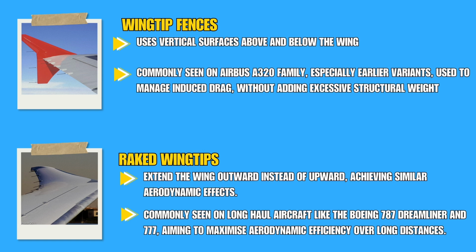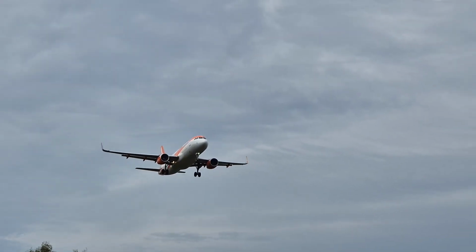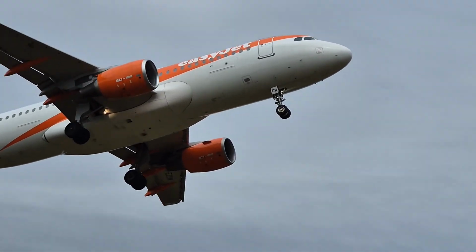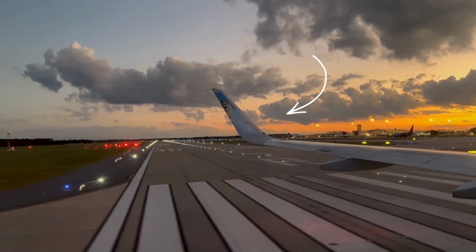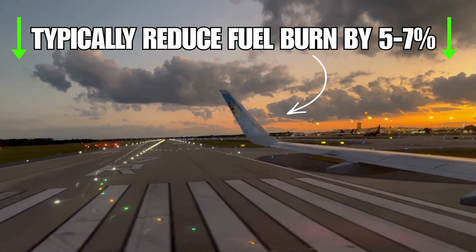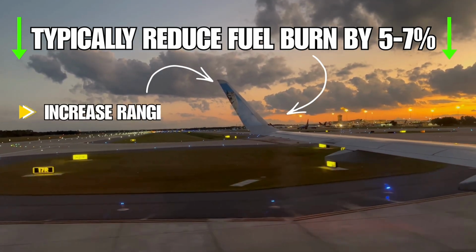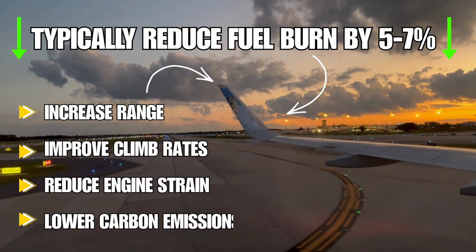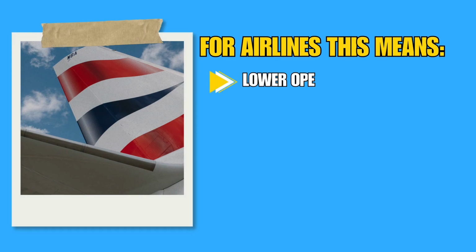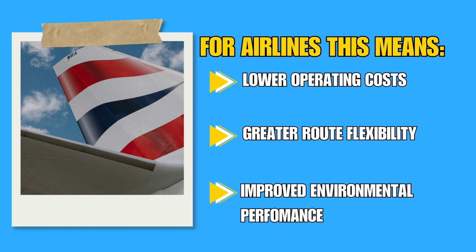Each design represents a different philosophy. Some prioritize maximum efficiency. Some balance weight and cost. Others are tailored for specific flight regimes. There is no universal solution, only optimized compromises. Winglets typically reduce fuel burn by 5 to 7%. But that number doesn't tell the full story. They also increase range, improve climb rates, reduce engine strain, and even lower carbon emissions. For airlines, this means lower operating costs, greater route flexibility, and improved environmental performance. Over millions of flights, these benefits scale enormously.